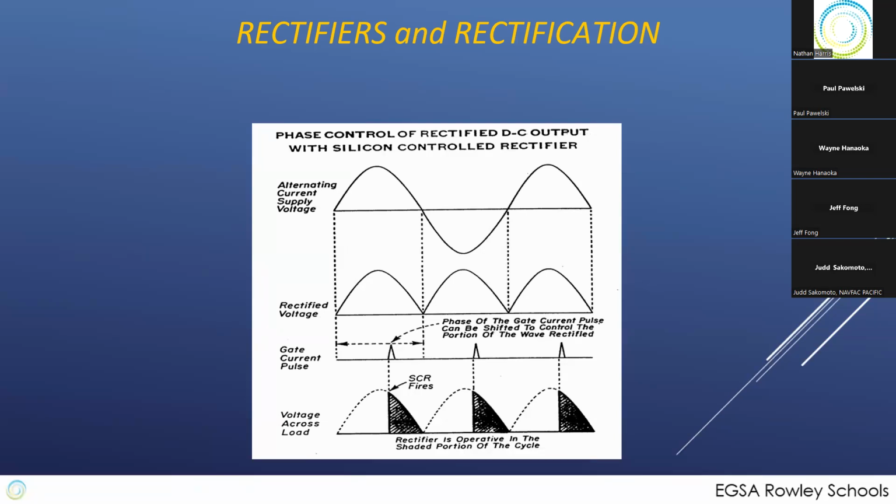Well, all of those big holes need to have very tight grids of basically welded together metal tubes in order to make a ground that runs through the whole thing. This is what keeps the EM pulse from coming in, hitting that, and actually shorting out the electronics that control the generator and the engine.